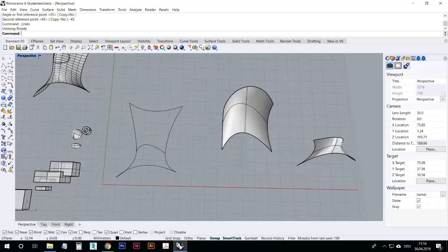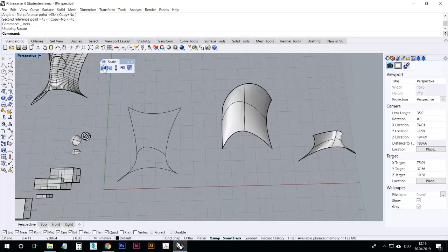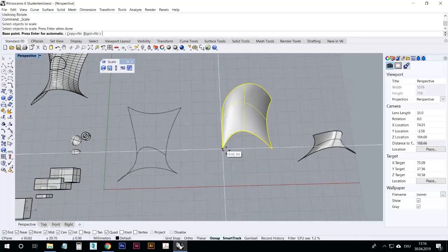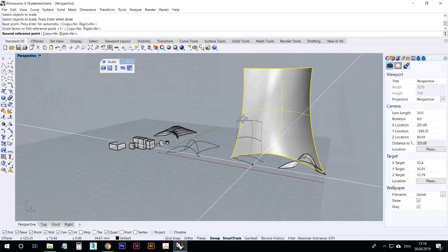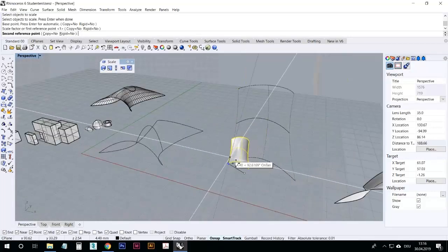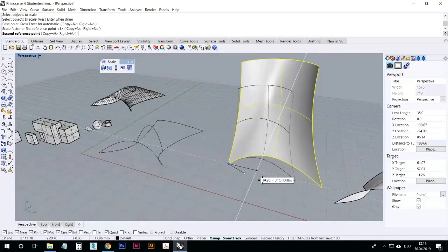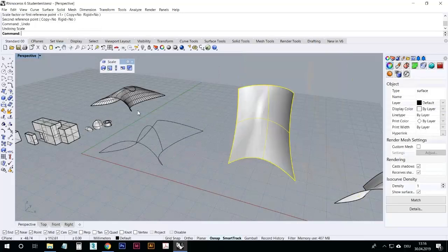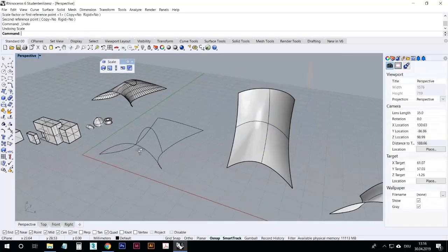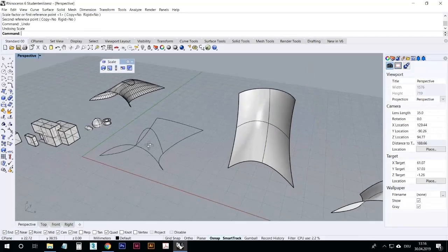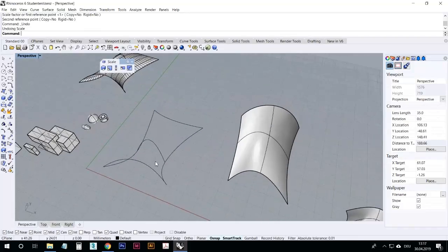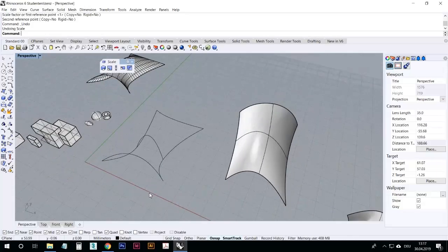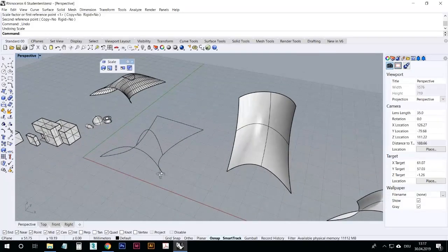You can also scale things here. You have a quite good scaling version. This is something I use quite often. So this is 3D scale, which means the shape will just grow in all directions, like this. All right. If I go back, I can show you instead 2D scale. That means it would only scale in X and Y direction, because I'm in the perspective viewport. And the perspective viewport is controlled by the top view actually, so it means that X and Y, that's the main, that's where all these commands are being executed.